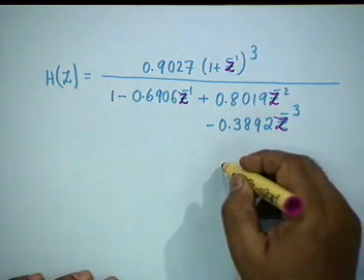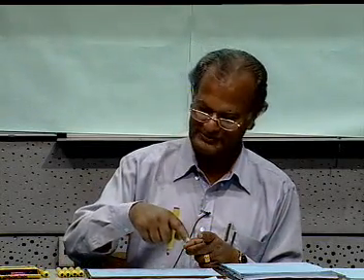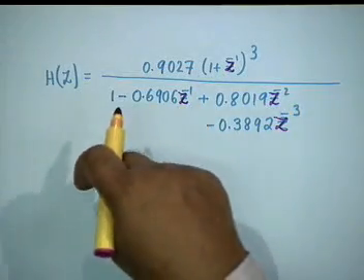Well, we showed these two alternative routes. One is you can go from digital specs to analog specs, then to an analog low pass filter normalized, then transform it to analog other kind, then put bilinear. You interchange these two steps here. That is, from the normalized analog filter you apply bilinear transform.